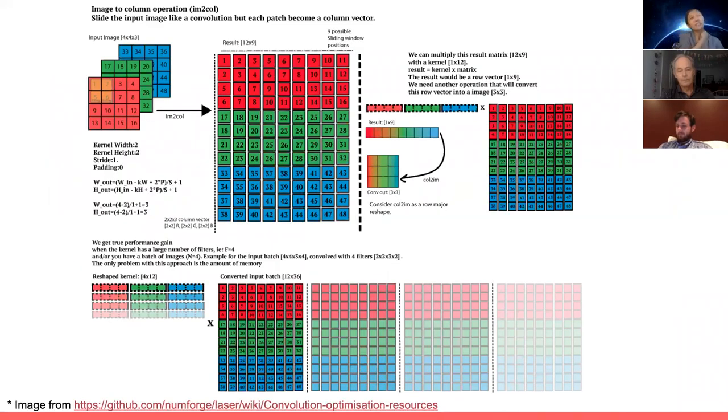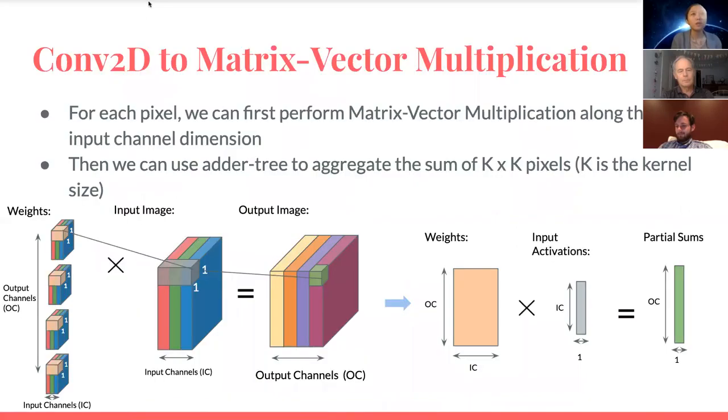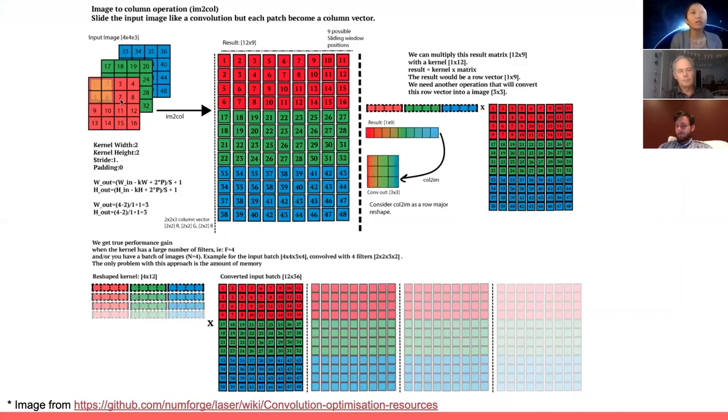So here's a more detailed illustration of how this is being mapped. For example, for the first convolution we need to compute, all it does is a dot product of this 2x2 receptive field. And how it gets flattened is we put 1, 2, 5, 6 into one column of this input matrix. Then the second input value that we need to convolve the weights with will be, I have an animation here, 2, 3, 6, 7. So we also flatten them out into this input matrix column.